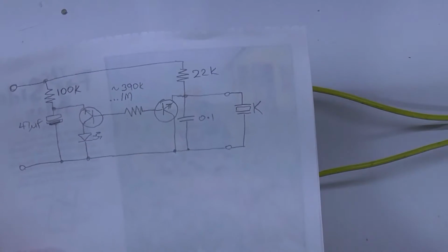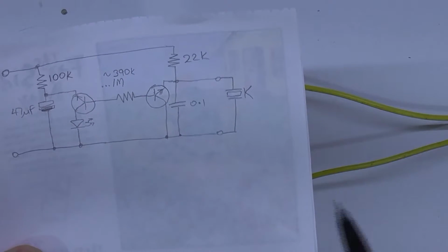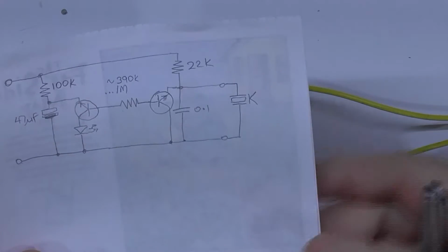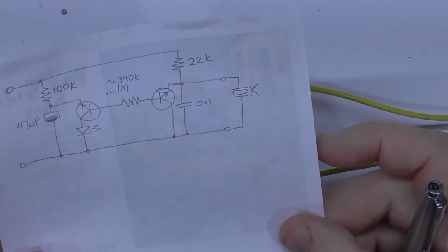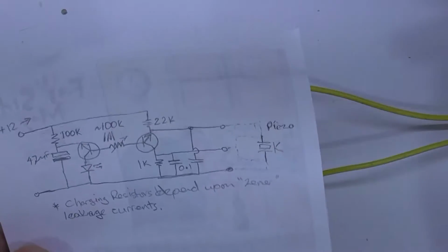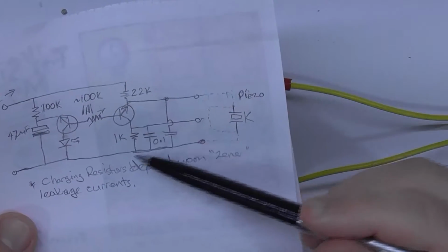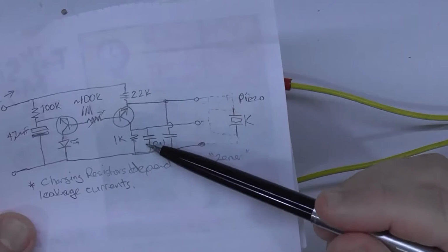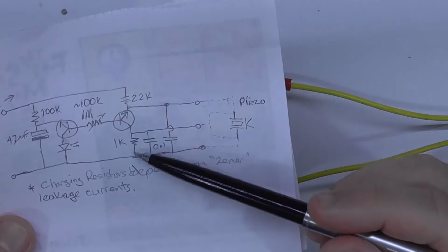What I did obviously was to put an LED in there as well, and I did try that, and it worked. But I decided that I needed something different. I didn't want to use another LED in there for no particular reason. So I eventually stumbled upon this addition to the collector circuit. I originally started off with a 1K resistor, and it would not oscillate.